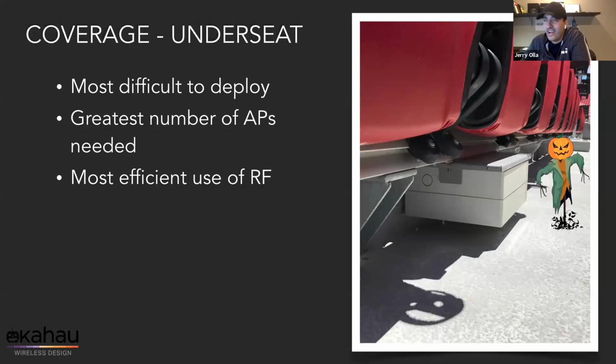All right. So Anders had a question around the radius. What is the typical radius of an AP in an underseat design? So that's largely going to... Yeah. If we're talking about the usable signal level right out of an access point, that's going to fluctuate depending upon each stadium. What is your intended coverage area? What is the power level of the access point set to? What is the gain of the antenna? Because we're concerned with what our coverage is, both from a power perspective as well as from a physical RF perspective, of how large a net, if you will, we are casting.